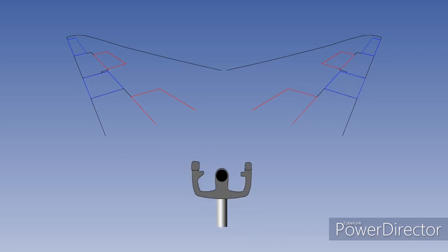Roll spoilers have several advantages over ailerons. Roll spoilers eliminate adverse aileron yaw. Roll spoilers do not twist the wing. Roll spoilers do not develop flutter. Roll spoilers do not take up space on the trailing edge, leaving it usable for flaps. Because spoilers work by reducing lift, their use will always result in a net loss of lift on the wing. This is not normally a significant disadvantage.